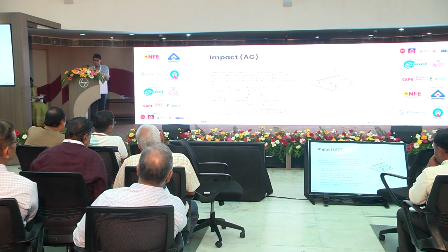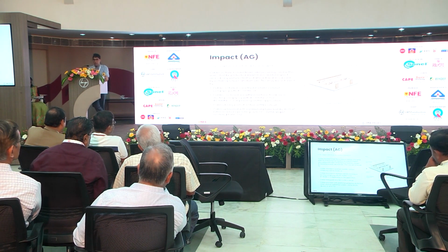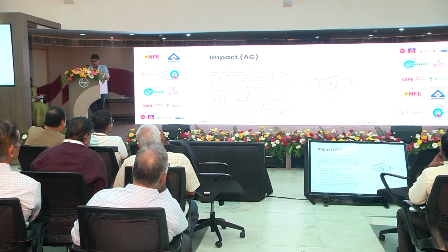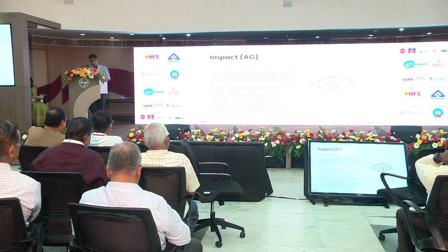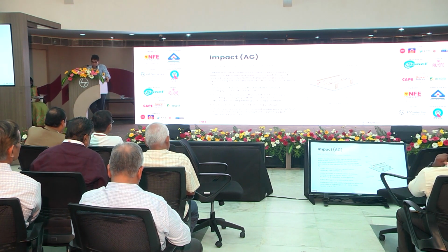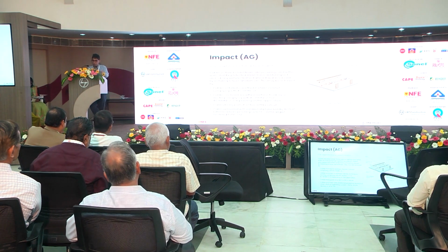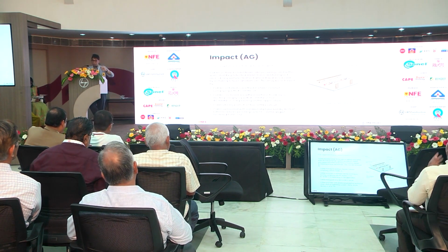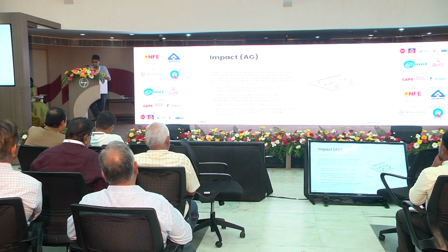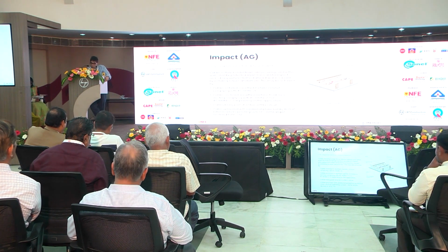So this is a very common arrangement, again, these modular homes where you've got wooden or aluminum panels, and you've got a floor here and a roof. This is your roof, this is your gypsum from the previous floor, and this is your current floor. So here you have a metal pipe that is put, an earth metallic conduit to 61386 part 21. Or you have to make the hole 50 millimeters from the top or the bottom, again assuring the structural integrity is not affected. Or you can use a metal plate like this that will prevent damage.